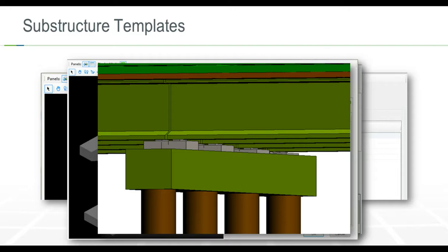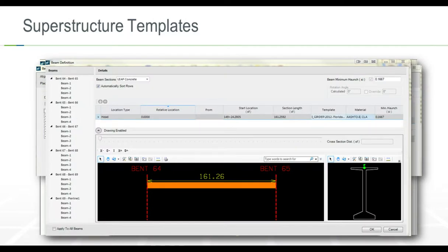We can manipulate those elements to get them to fit the design intent. Raul showed you a little bit earlier, and this is another example of some of the different types of piers that you can generate straight out of the box. Really, there is practically no limit to what you can do. And here's an actual sample of one of the substructure bents on the Bonner Bridge, and you can see the cast-in-place pedestals and the bearings. If you note, there are varying pedestal elevations. So in OBM, based on the bridge type, I can set the pier caps to either be sloped or flat, or adjust those to fit specific elevations depending on the need.